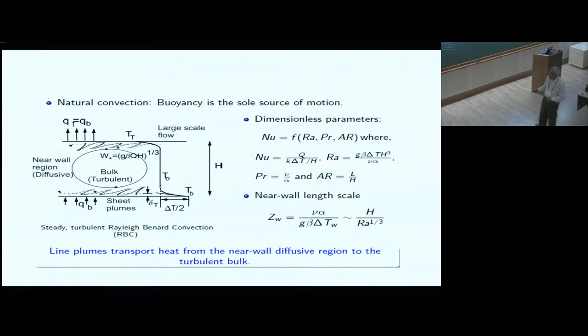But I feel if you want to describe near wall flows, this is the appropriate length scale to use. Just like in turbulent boundary layers, the length scale is the near wall scales, that is y plus and u plus. And there again you would use a velocity scale and a viscous length scale to non-dimensionalize the velocities and distances.